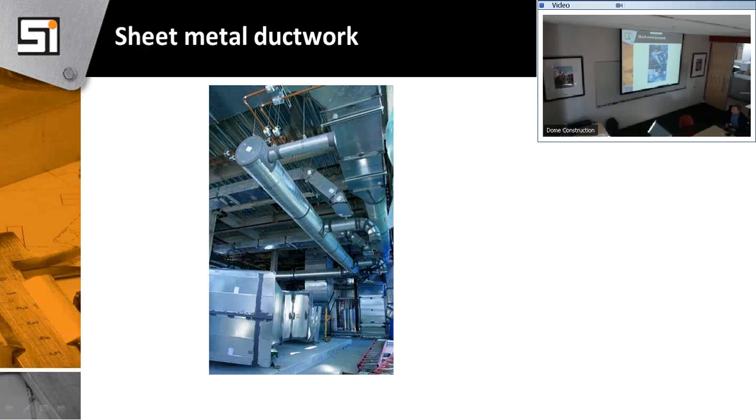With a rectangular duct, first of all, typically the joints are 5-foot joints. And now we do have machines that will cut it and break it, and that creates some of the cost. So when you're saying we're too expensive, we're buying machines that do this. But anyway, now I'm handling 5-foot joints, and I'm handling 4-sided joints too. So I have a lot of field work here, and now I have more elaborate support. A lot of the time I have to strap this stuff. So it's not only the cost of the material and making it, it's that installation is cheaper also.